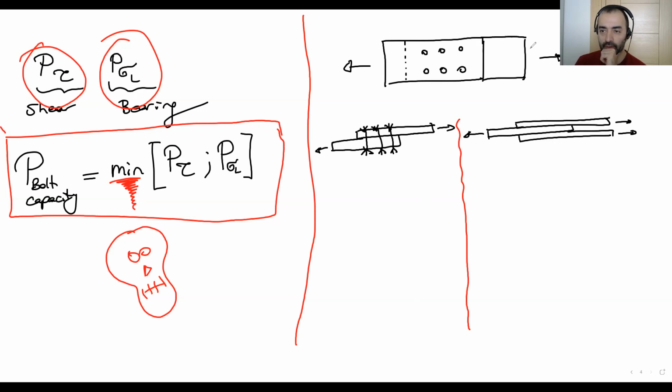So for the steel plate, it's an axial force, because this is the area for steel. This force is perpendicular to the steel area. So at the end of the day, this is an axial stress check for the steel member.